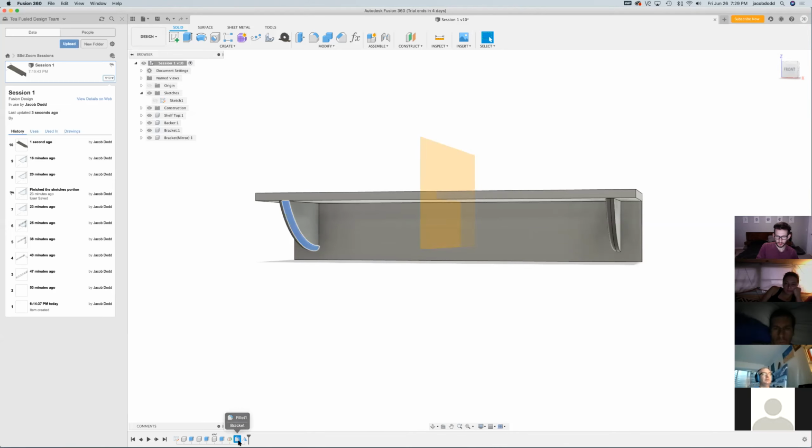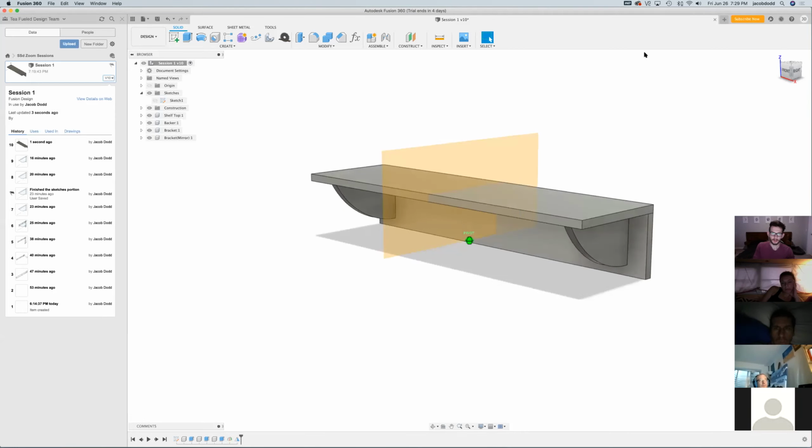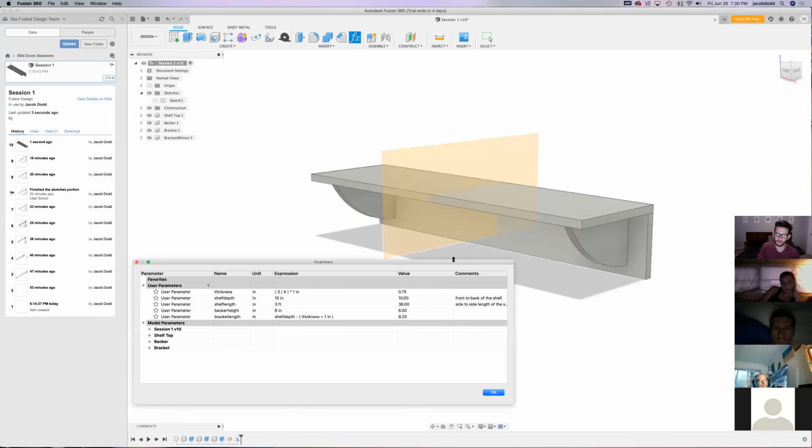And there's only certain things you can do as well. So I cannot drag this operation that we did back past the creation of this object, obviously, because it will not allow, you can't fillet an edge or round over an edge that doesn't exist. And the same with this mirror. I cannot take it back further than this shelf creation, because we referenced two sides of the shelf to create that mirror. So I'm going to remove that fillet because there's no real need for it. So that's kind of where the parameters come into play.